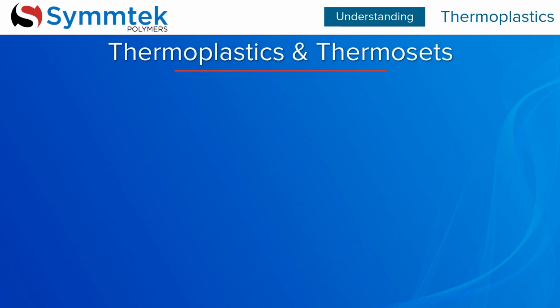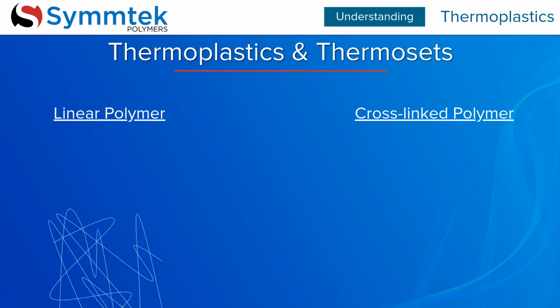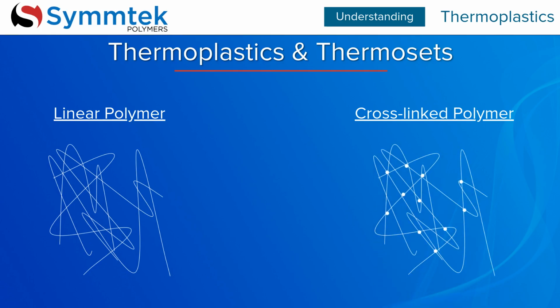The differences in thermoplastics and thermosets help us understand the structure of polymers. Polymers have the capability to have linear structures as well as cross-linked structures. A thermoplastic is a linear polymer that can be melted, solidified, and remelted several times. A cross-linked polymer, or a thermoset, is a polymer material that once melted goes through a process of cross-linking and cannot be melted again.